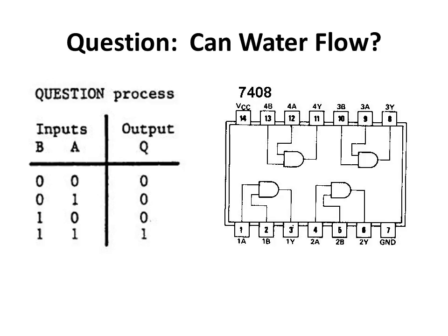We can go back to early 1970s technology and use a simple integrated circuit whose pin diagram I show you, and there are 4 2-input AND gates, which means you can ask 4 separate questions using this chip.